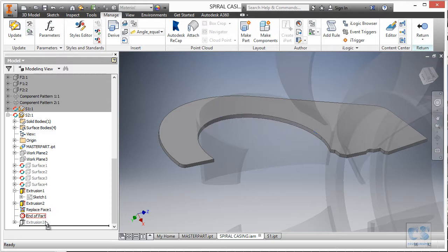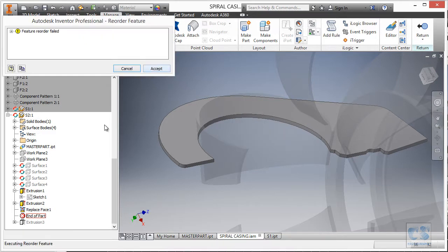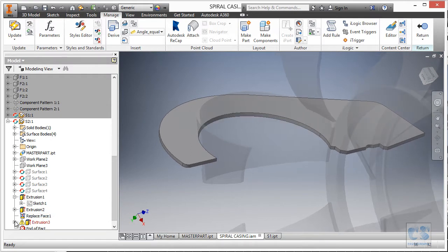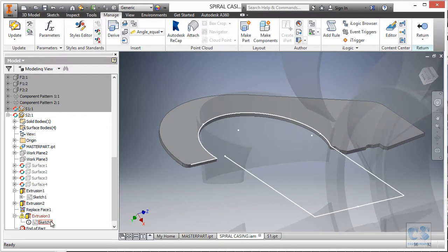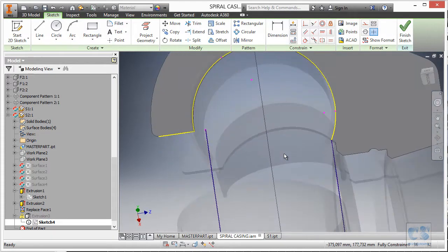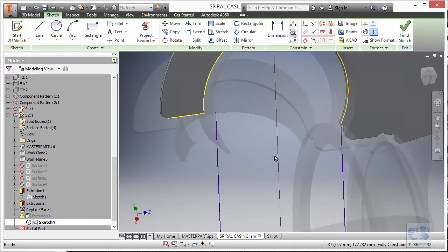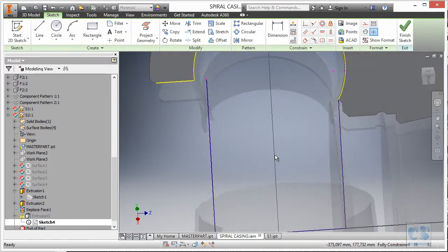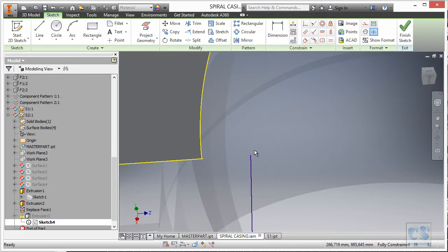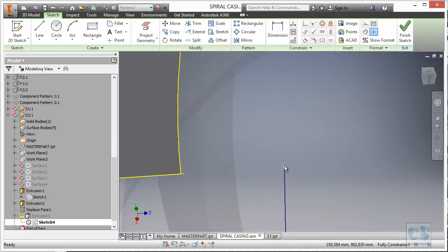Now let's go for the final extrusion, and as you can see, we have a failure. We accept it, and we are going to have a look into the sketch to see what is going wrong. Right away, you can see that we have a set of pink dots in the sketch. This is not good. They usually indicate that a link to an old reference geometry is broken and related constraints cannot be solved. We have no other choice than to delete them.